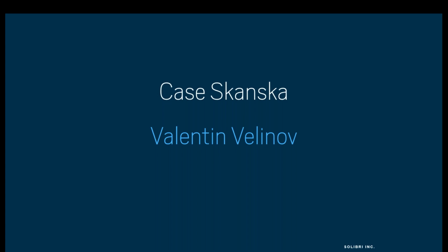Then there's a question from Mayank. Do you use BCF format for issue reporting? If yes, what do you think are the advantages of that in model communication during the design phase, and which software tool do you use to collaborate between Solibri and other design software? We actually report in different ways. BCF format is one, and that's the one we prefer, because designers can utilize it in their native modeling software as well. But some of the designers prefer an Excel export of the report, so we submit it that way as well. The BCF is good because you can basically update the statuses for different issues in that one same format. It's really easy to sync between different platforms.